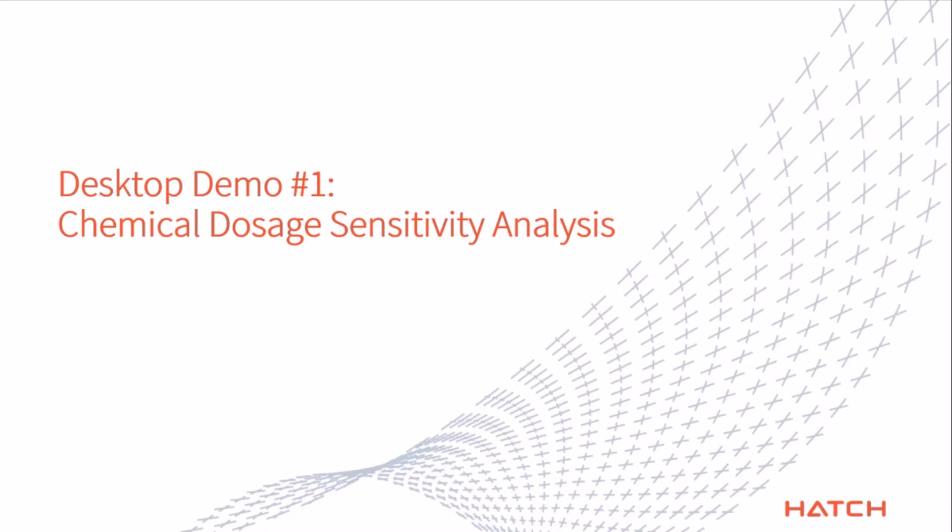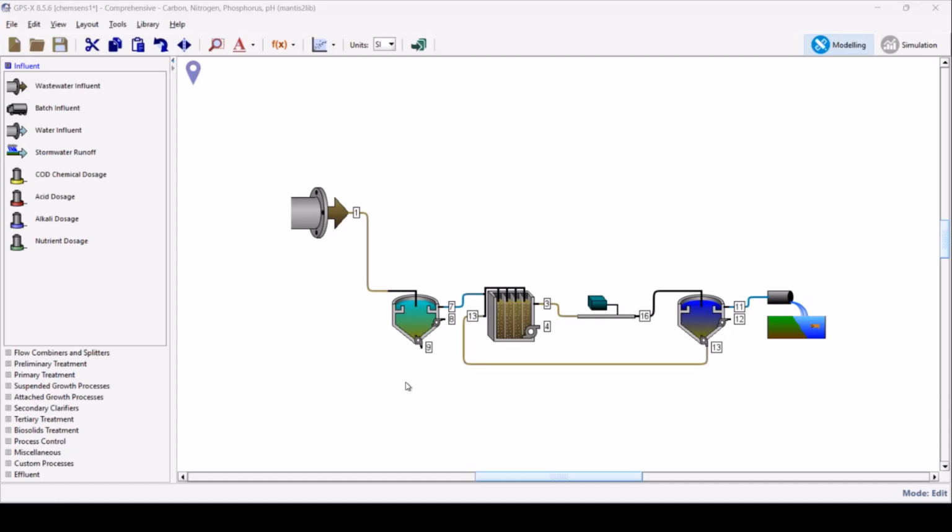And I'm going to do a quick demo here just to show you how things look when you use the inline chemical dosage object. So let me close this and go to my copy of GPS-X. Just to give you a sense of what we're doing here, this is a conventional activated sludge tank. So our influent, primary clarifier, plug flow activated sludge unit, then our inline chemical dosage object, and a secondary clarifier with the recycle, and then our effluent.